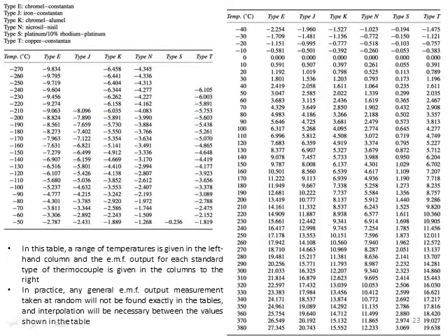These are examples of tables for different type thermocouples, type E, J, K, N, S, T, and the type is located in the upper left-hand corner. You can see here in the left column you have the particular temperature, which ranges from minus 270 to 380. And then in each column you'll see what voltage each temperature will give for each different type of sensor.